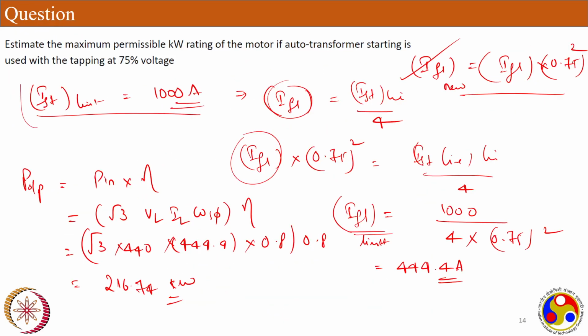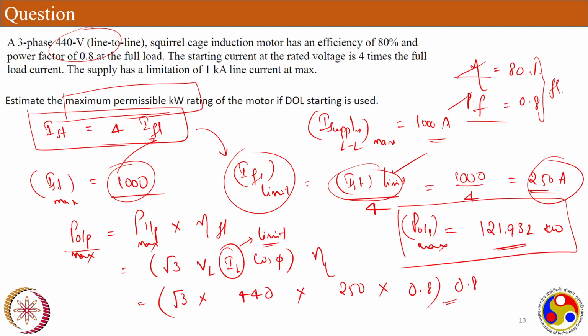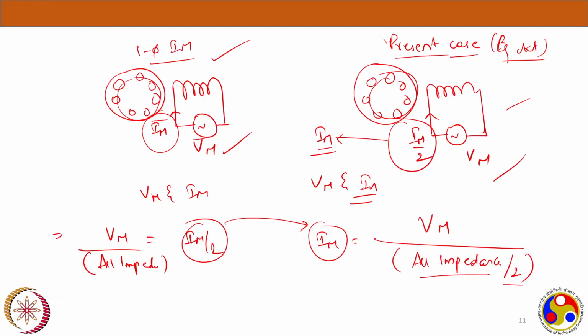Anyway, getting back to our single phase induction machine, I want to close the discussion with even more clarity on how exactly it behaves as a single phase induction machine. The takeaway points would be: in the single phase induction machine, there won't be starting torque. Starting torque is zero, but running torque would be there. So what I want to convey from today's discussion is, we just now arrived at the equations of the single phase induction motor, and this is what we have, right?